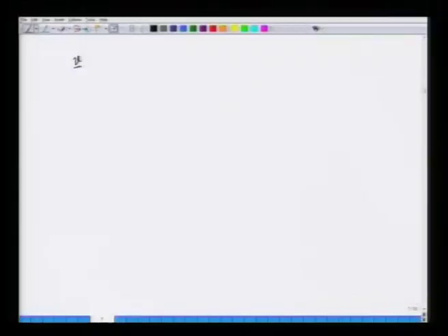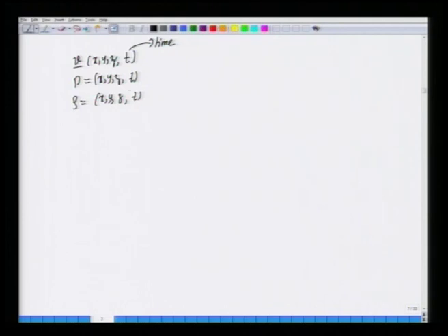Once you use that continuum framework, we will define velocity as a function of all the 3 coordinates in the fluid in the coordinate system, and time, pressure as a function of all the 3 coordinates and time, and density as smooth functions of all the 3 coordinates and time. These are called fields, continuum fields. So, these go by the name of fields, and we assume that they all can be differentiated easily; they are differentiable, smooth and continuous.